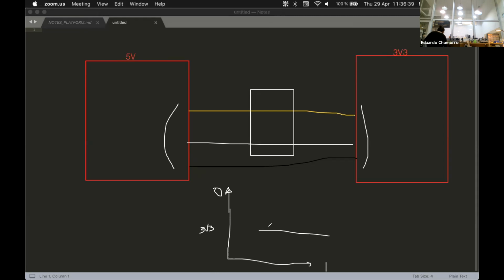You have the USB in the 5, and the USB is giving 5 in here. So the LDO is going to convert down to here and give you 3.3. If you have 3.3, it might not work because normally if you input 3.3 into the LDO, normally LDOs have 0.9 to 1.5 volts of range that they need in extra so that they can make the conversion. So around here is your limit, and above it's fine.